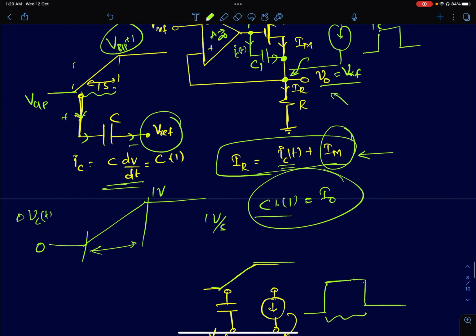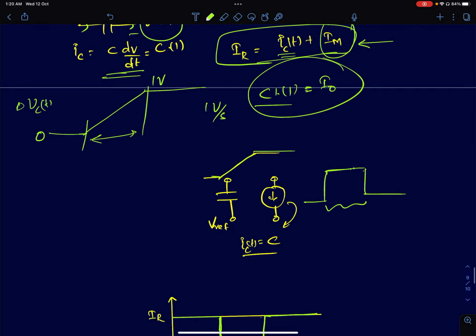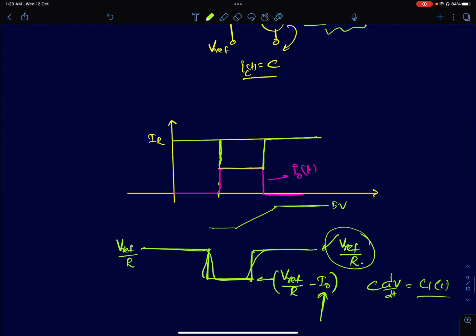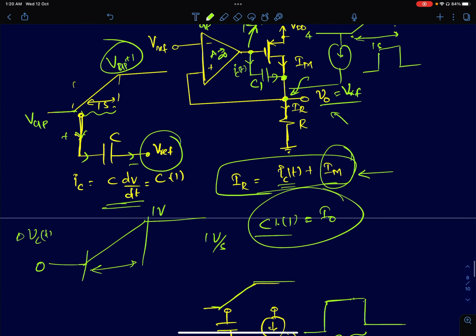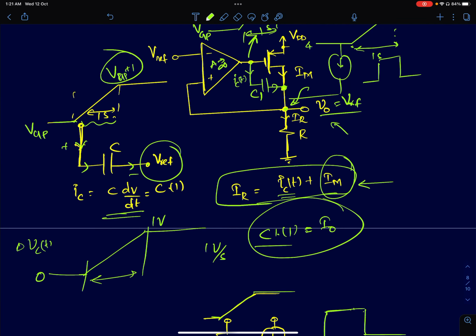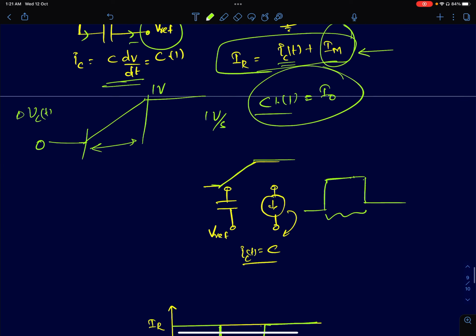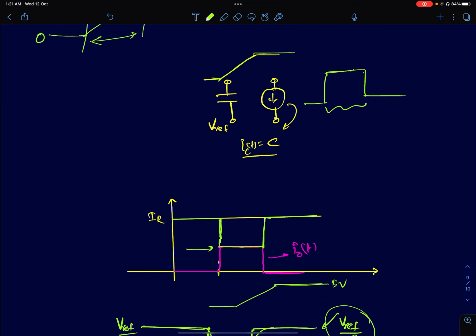This is all, I believe, the person who designed it would have thought of in this direction, and wanted to see your understanding of what happens when I introduce a capacitor. So it's mainly testing that. What it's essentially doing is adding a pulsed current source. Your MOSFET's current will decrease by that amount, which is determined by the capacitor's current, and then it will recover back to its nominal value.